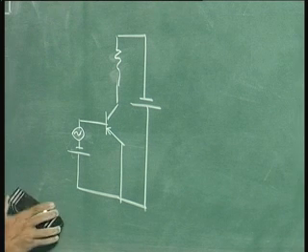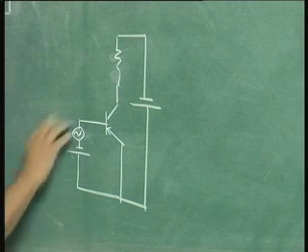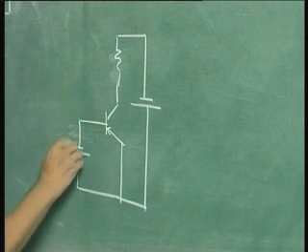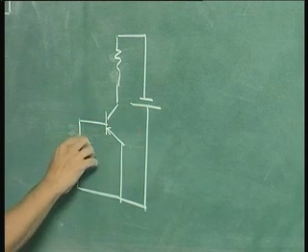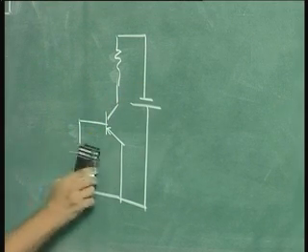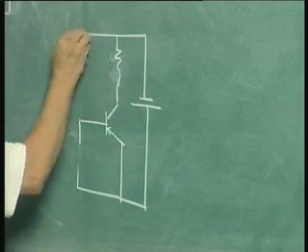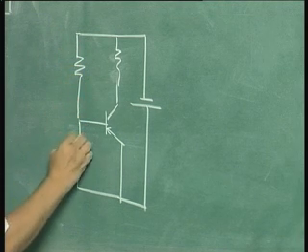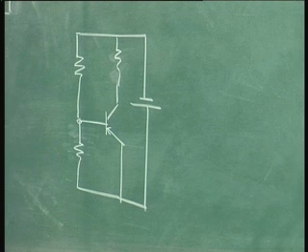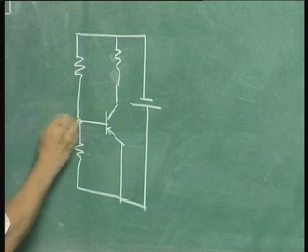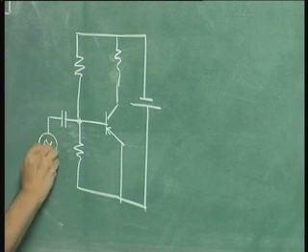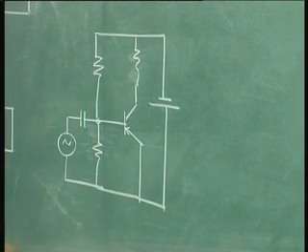Now for that purpose, what we do is we modify this whole circuit a little bit on this side. First, for the DC conditions, instead of having one power supply here, another here, since this power supply is smaller than this power supply, we can derive this from here as a resistance divider. So from this power supply we use a resistance divider to get this required voltage here, and now this we use as the input terminal, and we couple the AC voltage through this coupling capacitor.